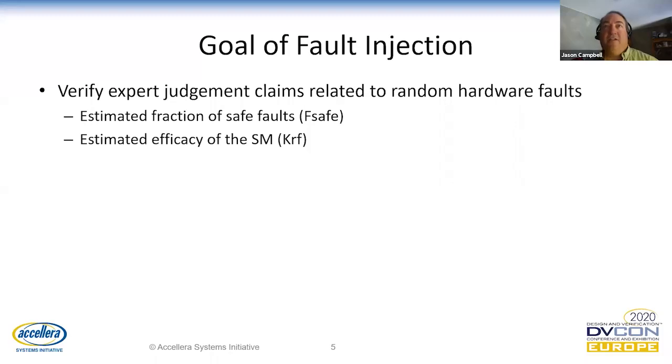There's actually not a lot of safe faults in a design. If you think about even logic which you say is unused, a lot of people will call that safe, but it's really not safe, because faults that happen in that logic could suddenly make that logic become active. Therefore, I think personally, there's no such thing as 100% safe. So at NVIDIA, we make everything at 99. But then we also measure the efficacy of that safety mechanism, to verify that claim.